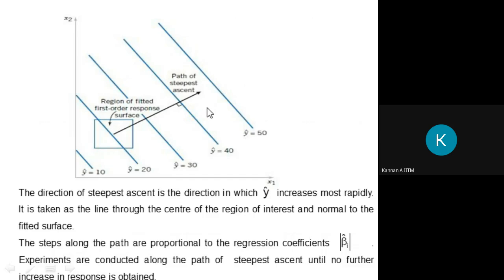That is something which you cannot do. Your model, whatever correlation or empirical equation you are developing, is only applicable for the region or the range of experimental data conditions in which it was developed. You cannot extrapolate it because you did not do experiments beyond that particular region.